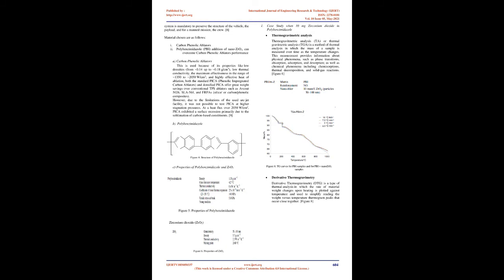4. Heat of ablation. The heat of ablation is defined as the ability of a material to serve as a heat protection element in a severe thermal environment. The heat of ablation value should be as high as possible to minimize the weight of material required to accommodate the incident flux. The strength of the ablative material should be high to withstand the mechanical forces of the environment.